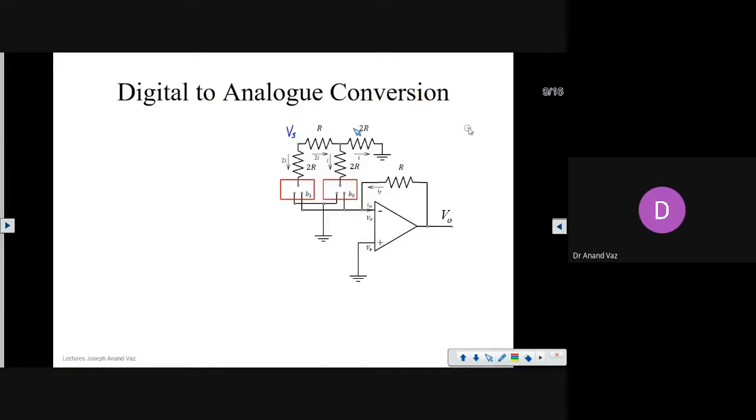So again, in this case now, you are going to have the current that is 2I plus 2I, that is 4I current, and this current will be equal to Vs divided by R, because as far as the equivalent resistance is concerned, this end is connected to Vs and this end is connected through the equivalent resistance R to 0 volts, and so the current that is passing through this is now equal to 4I.